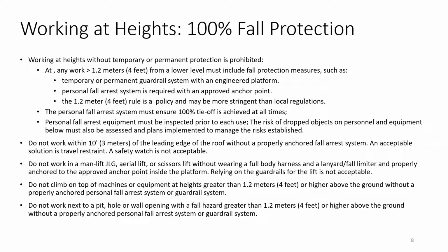The 1.2 meter or 4 foot rule is a policy, and we may be more stringent than local regulations. The personal fall arrest system must ensure 100% tie-off is achieved at all times. Personal fall arrest equipment must be inspected prior to each use. The risk of dropping objects on personnel or equipment below must be assessed, and plans implemented to mitigate these